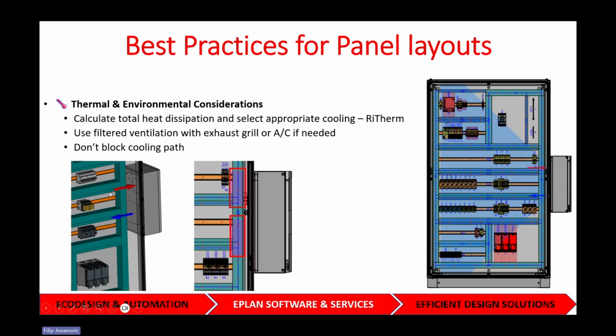So for example, you can see the blue arrow, you can see arrows here, as well as the trunking blocking here. And all the way to the right side, you can see the airflow path. So what this tells me is my third VSD is not receiving the full airflow, not being cooled properly. So now I have two options. I can either lower the AC, position-wise, or I can use a flow diverter. So all VSDs are properly cooled.